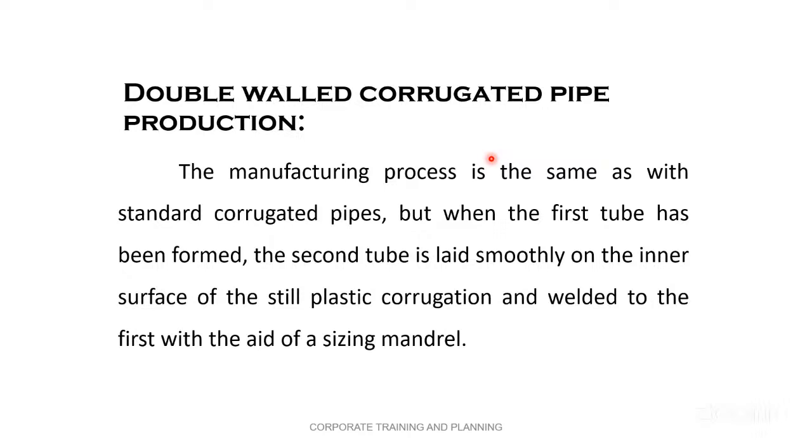A question regarding extrusion: is there any relation between melt pressure, temperature, and load? You have any sheet to understand about it? No, it differs from material to material, because I told you regarding PVC, the pressure is the same there. It is just by practice only, friend. You have to maintain the air pressure inside. There is an air pressure gauge, by which you can measure the pressure and maintain the same pressure for your whole process.